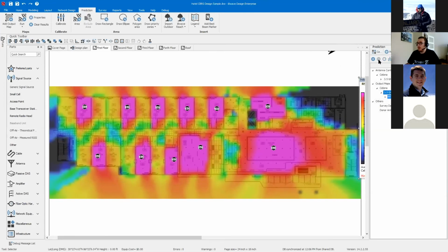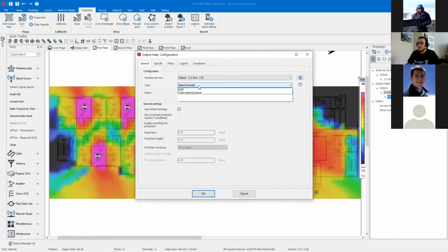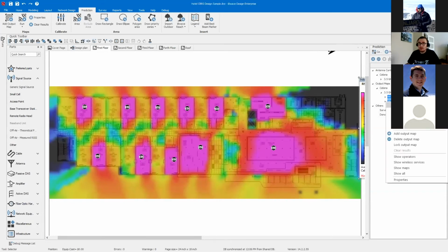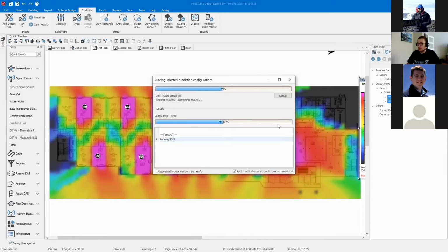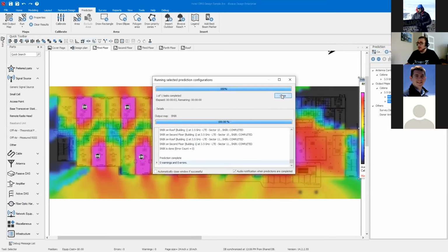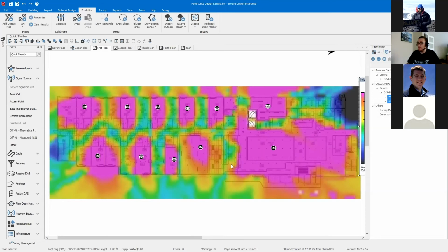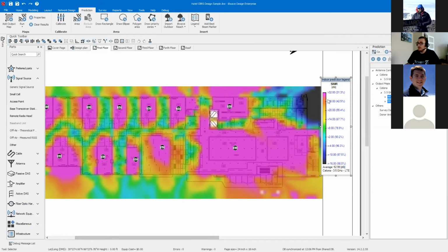And the other most important map is the SINR map. So if I go to SINR, combine the system again, and again, this is worst case scenario. We only have one channel that we can reuse. Ideal scenario, you would have multiple channels that you could reuse, the same as in Wi-Fi. So this is my channel, my SINR map. You see when you are close to the small cell itself, the SINR is good. You see it's like 30 dB or higher. As soon as I get between the small cells, then the SINR degrades, and it's closer to 8 and then degrades all the way down to 2.